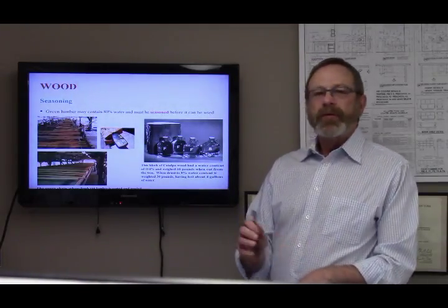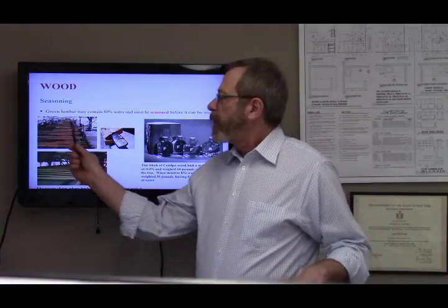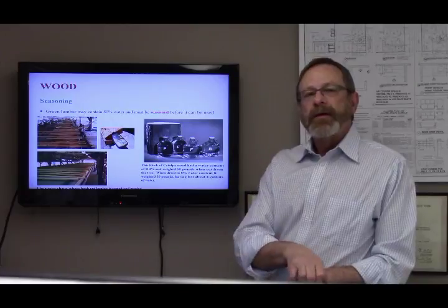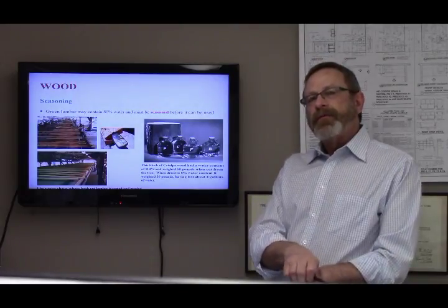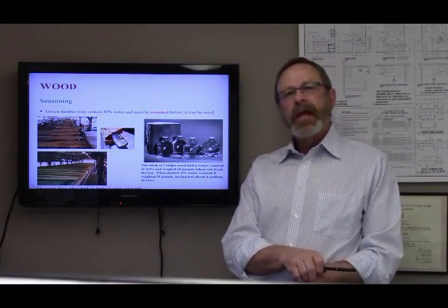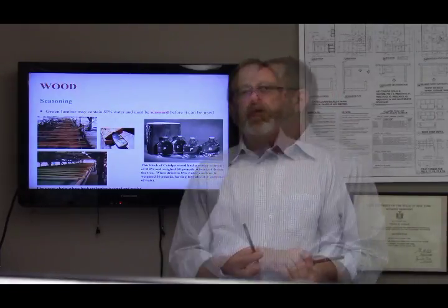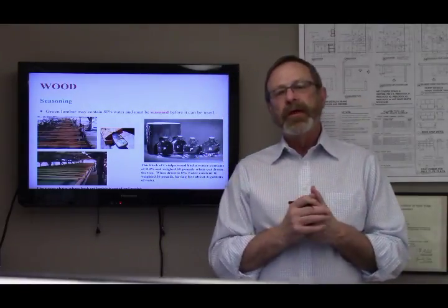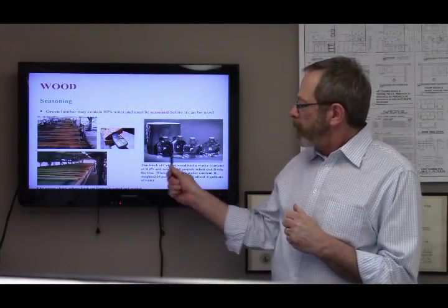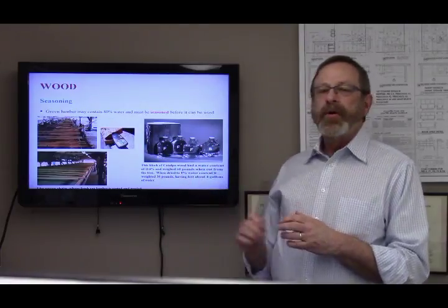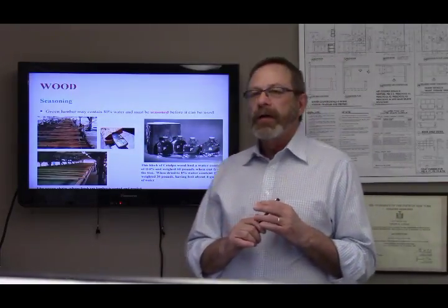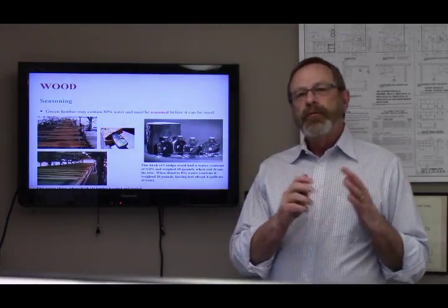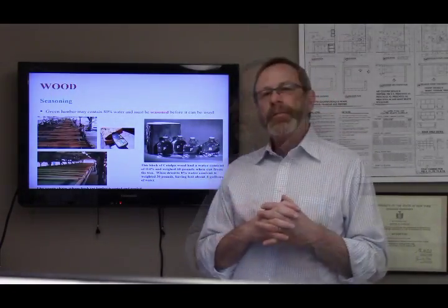We've talked about the actual and nominal dimensions of lumber due to the shrinking process from when it is first harvested. When it's first harvested, we're calling that wood the green lumber, and it has maybe 80% water content. In the process of being sold to the consumer, that lumber has to be dried. So we call that seasoning the lumber, so that it can be dried to within 10% water content. This log contains that much water, so there's a lot of water to be drawn out of the wood so that it can be shipped to a job where it won't move or shrink or expand once it's been installed.